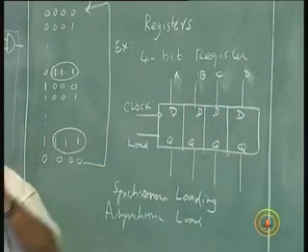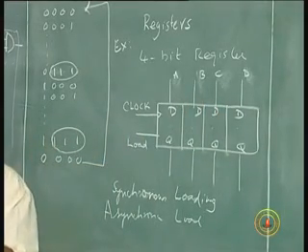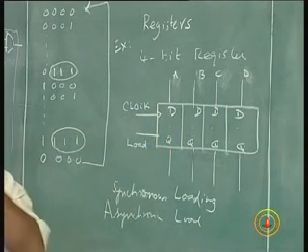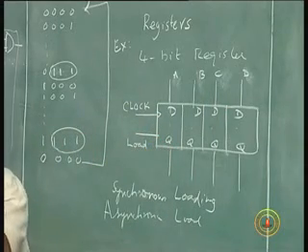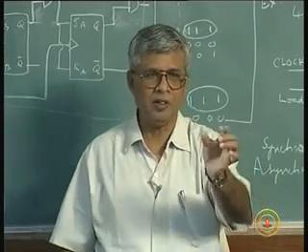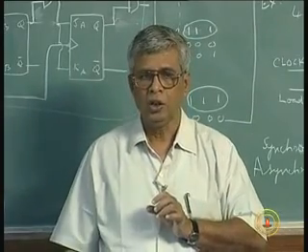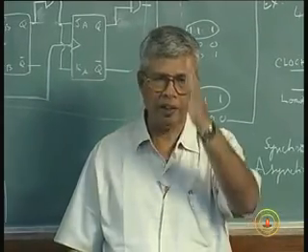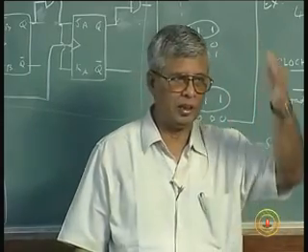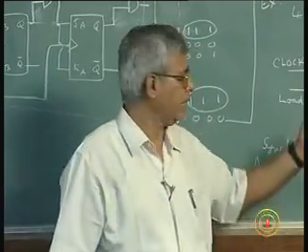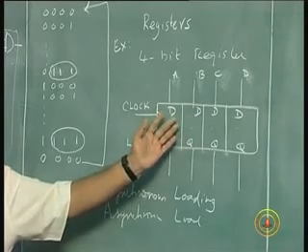Even when the clock comes at a very fast rate, much faster than the rate at which I want to read from this memory. Give an example. I have a clock of, let us say, 1 megahertz. That is, the clock period is 1 microsecond, so every microsecond we have an edge of the clock. Whereas I want to put the data here and keep it for 100 microseconds.